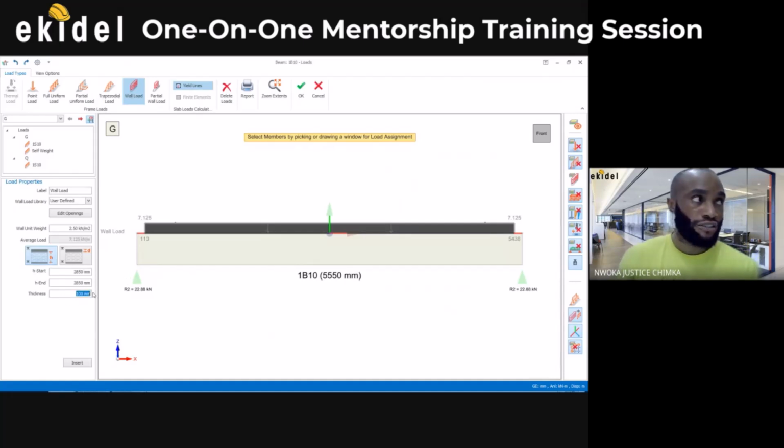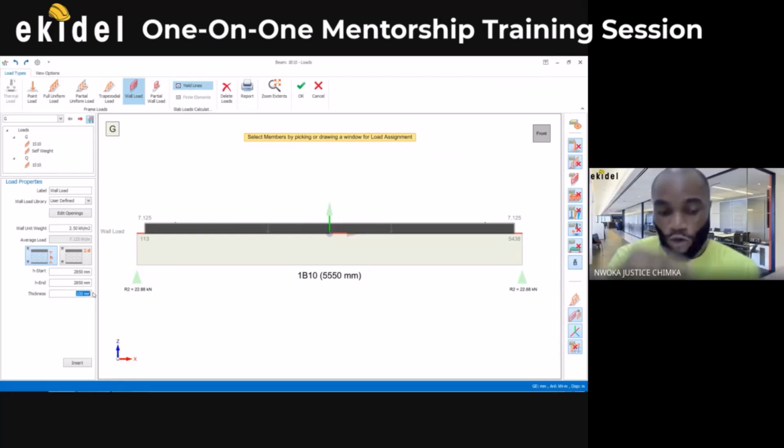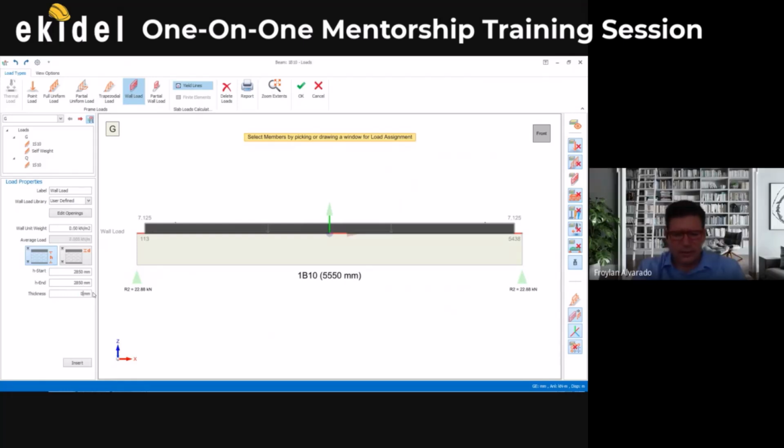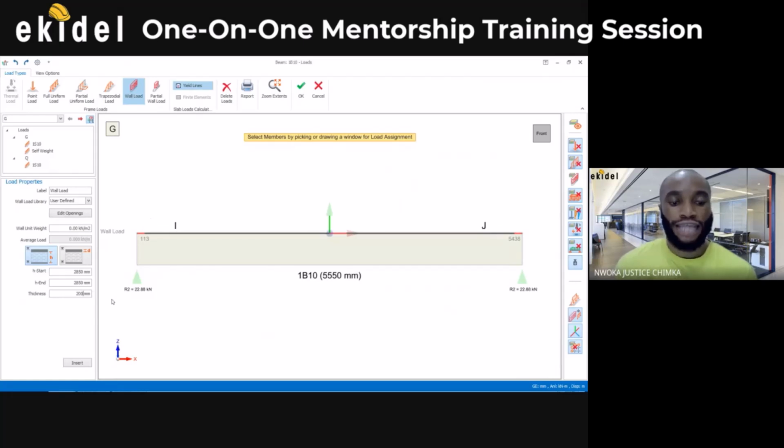Now you put the wall thickness. What's the wall thickness that you're using? I was telling you 200, right? 200. Well, 150. Yeah, 150, because no, it will be 200 with the plastering, no? Yeah, 200. So now put in the block wall thickness 200 here. And once I've done this, sorry, we didn't add this again. Let me put this 2.5 as the unit weight.